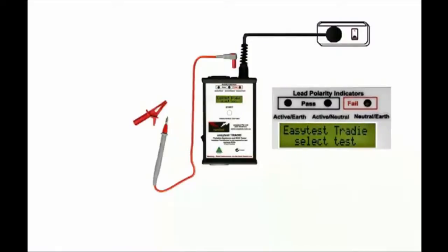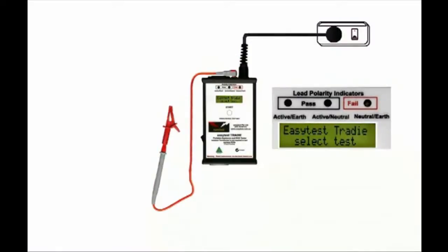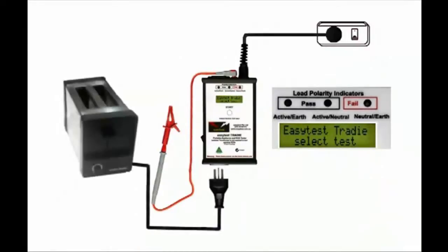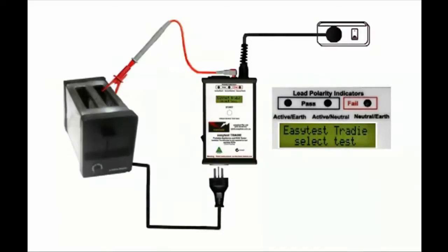We're going to test an earthed appliance. That's class 1. So we'll need a test probe to check the earth. In fact, the procedure is the same for class 1 and class 2. The difference lies in the interpretation of the results. The class 1 appliance in this case is a toaster, and it's safer to assume that the appliance may have a fault until we've tested it to prove otherwise. So firmly clamp the earth probe onto any exposed metal we can find. Check that the appliance and the tradie are both switched off, and plug in the appliance.